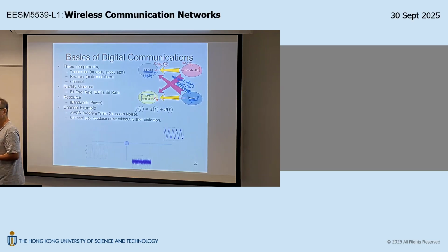Is that okay? So even though we are talking about physically the same power amplifier, with a maximum transmit power of 30 dBm, when your Wi-Fi transmitter is transmitting symbols with different modulation levels, the average power that they can transmit is actually different. This is because these different modulation levels have different peak to average ratios, so they need different back off. You understand my point? So even though they share the same physical power amplifier, their transmission power will still be different. This is because they have different back off.